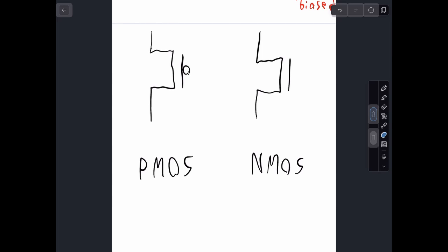So that means that the output is floating, and what we'll need to do is have something else set it. So right now, with the PMOS, it looks like the only actual function that it has is setting the output to 1. But the NMOS is cool because, if the gate is 0, then the drain will also be 0. Is that right? No, sorry, I'm confused. Okay, sorry. If the gate is 1, then the drain becomes 0. But if the gate is 0, then the drain becomes high impedance.